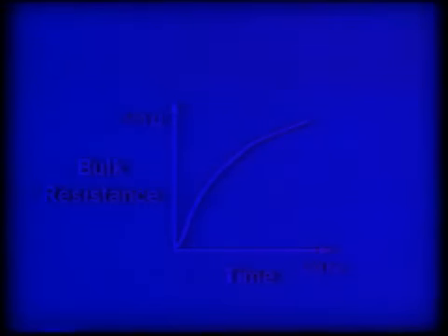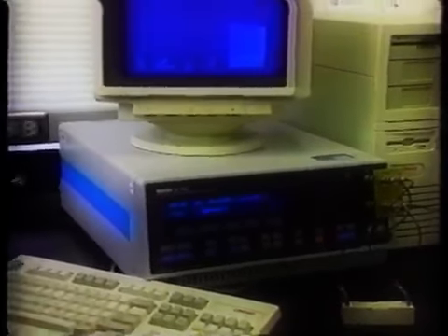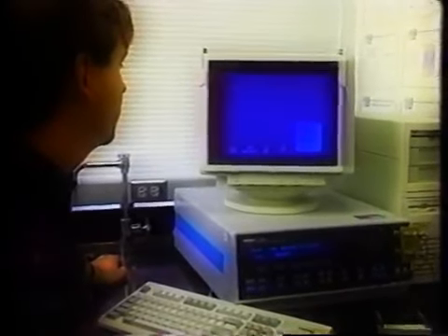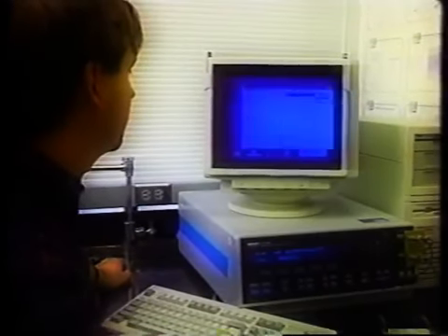At early ages, the water easily conducts current across the specimen. But when hydration products fill in the open spaces within the specimen, electrical current cannot pass as easily. In this way, the electrical properties can be related to the degree of hydration. The resistance and impedance of cement is a topic of research that may someday change the way we test fresh concrete in the field.